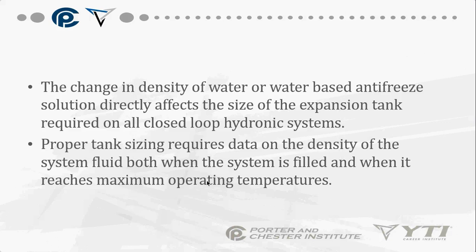But in a residential system, the average size house, not a mansion, going to glycol over a regular water system, would it really even be necessary to put a different expansion tank? I mean, the expansion difference is going to be very little in a small system like that. It would probably be a little bit of a difference.